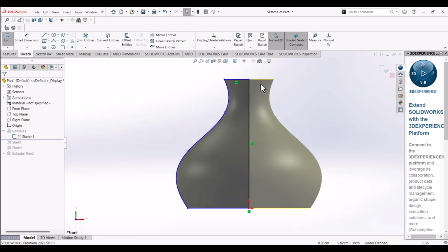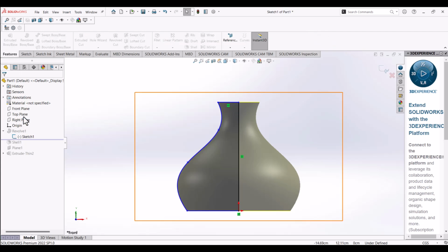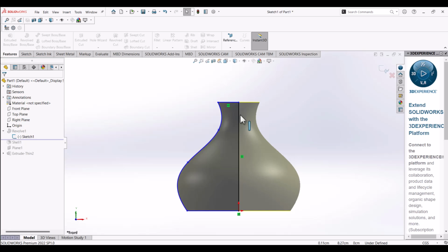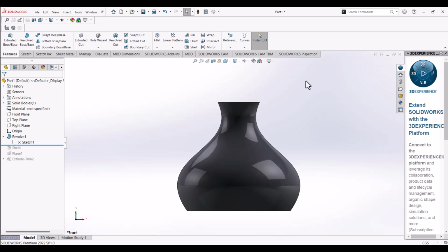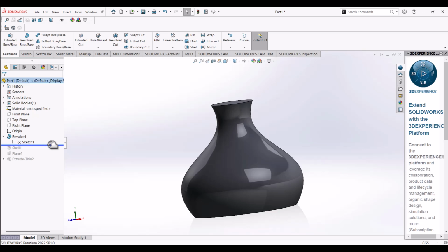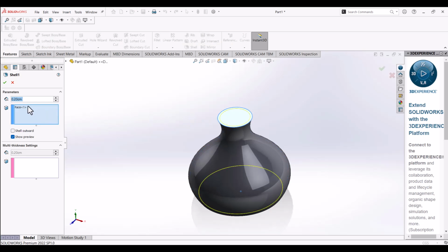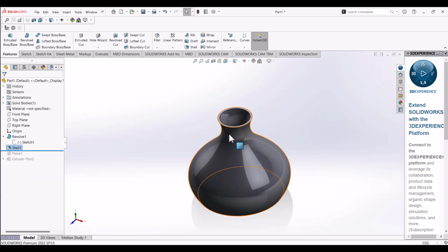I drew this shape, like how I did the first vessel. Then I came to revolve. So I revolved this using this as the axis, let me accept. When I revolved it, I got this. Then I moved further again. I did a shell from here. If I edit it, you can see that this was a shell I did of thickness 0.2. Then I accepted it, then I got this shape.